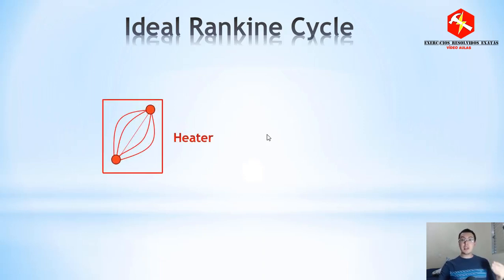First we have the heater. As the name says, it has the function to receive heat from another source. We can burn a fuel or use a solar panel, so the sun heats the fluid and puts more energy into the cycle. We also have a turbine. The turbine is responsible for producing the energy from the cycle: we expand the fluid, increasing its specific volume, and we produce power.